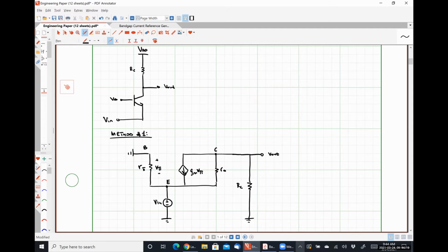So just looking at this real quick, we can see that V out is the exact same thing as the voltage drop over that resistor RC, since V out would be measured with respect to ground. Positive polarity terminal would be on top, negative polarity terminal down here at the ground. The current flowing through RC, so let's write this down.